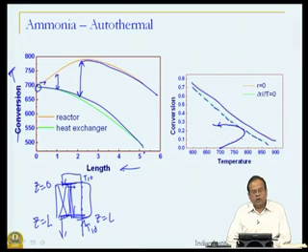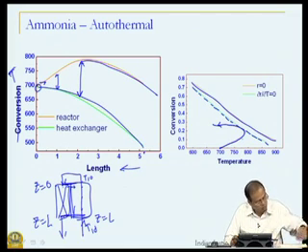But the autothermal reactor also leads to operation in which we have the possibility of multiple steady states, where, starting from the same feed temperature, we may actually have different outlet temperatures, and this is a fact that we have to keep in mind while designing the autothermal reactors.